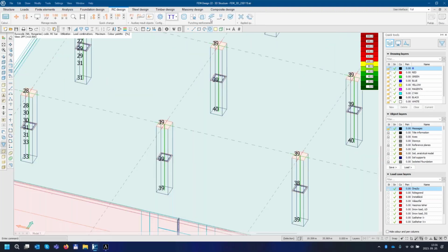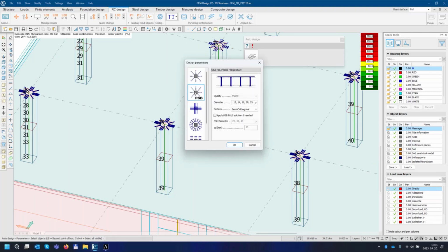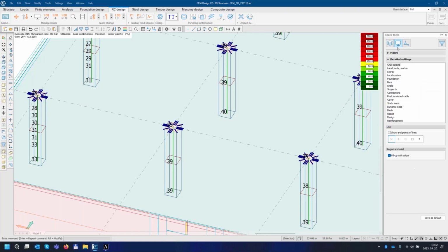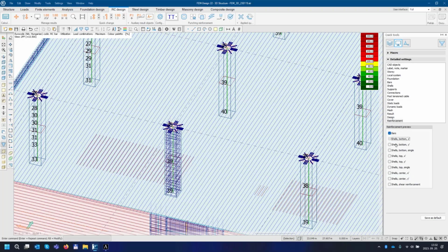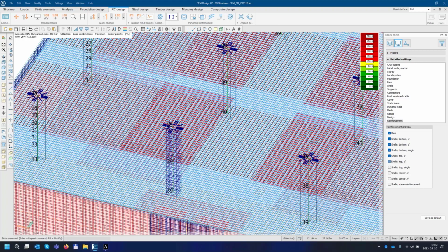For shear reinforcement and punching reinforcement, you have several possible ways in FEMDesign. For example, you can make this with strut rails, bandage rebars, or circular stirrups here. Okay, I have prepared a fully designed model for you, so I can show you that all the bars and reinforcement are in the elements here.